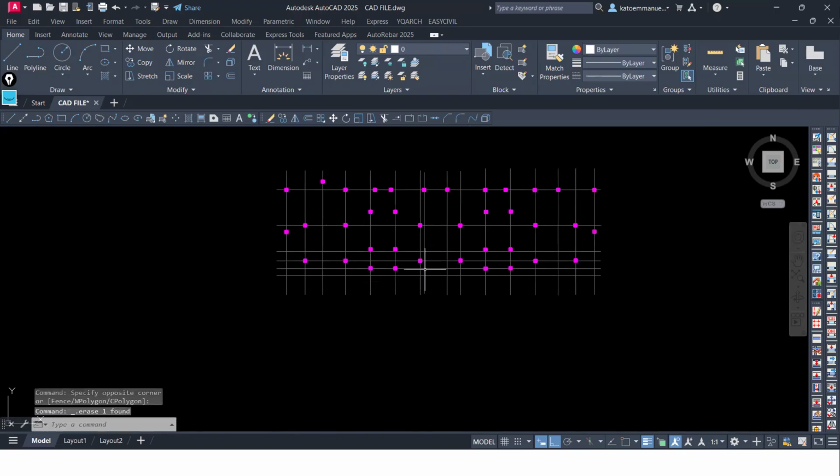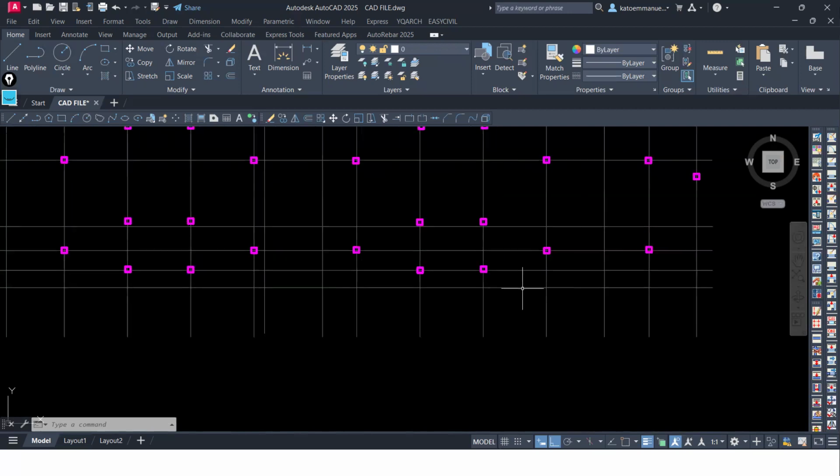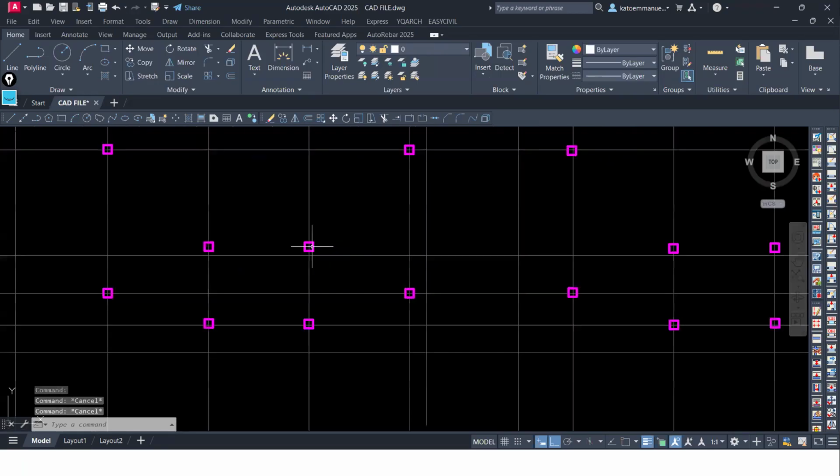So now you have this. That is columns and center. So that is what you need to work with in the structure, the dimensions. And these lines should be complete lines. Not having a line which is split here and then you continue it when it is split. No, it should be a complete line like that. These must be polylines or rectangles, closed loops.